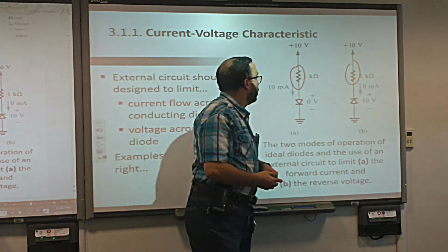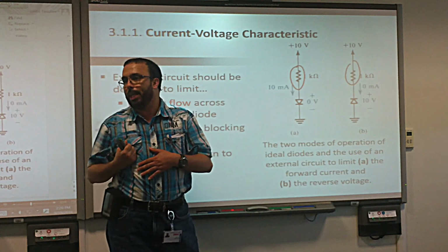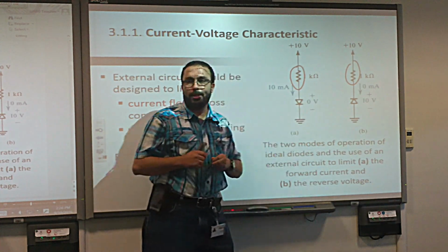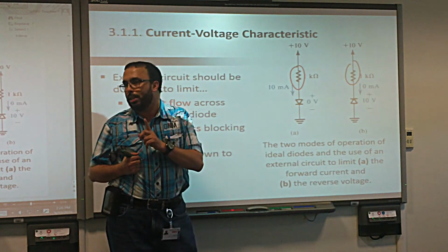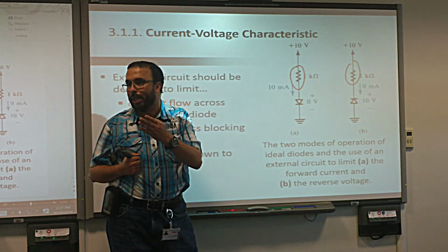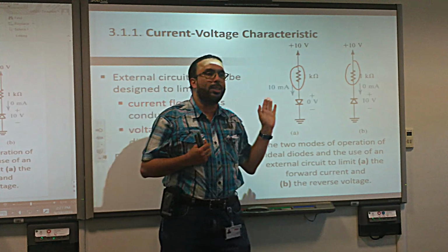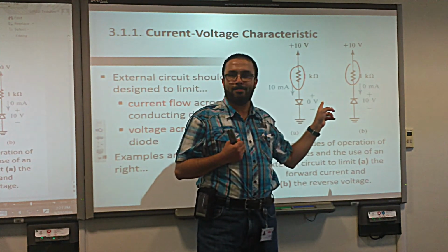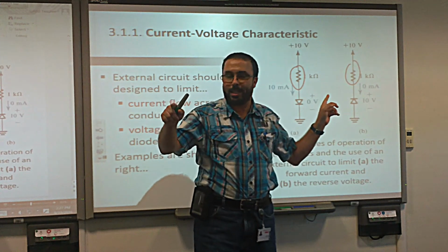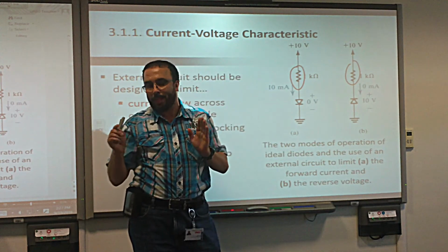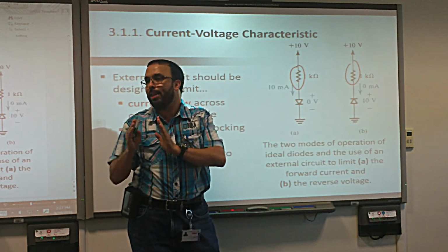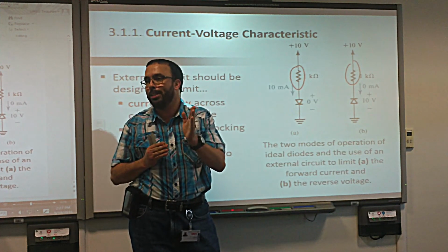Did we understand? So to study the diode behavior, we have to put what? A resistor in series with the diode. That means if the diode is in the short circuit form, or in forward bias, what's the role of the resistor in this case? Reduce the current. Exactly, limit. Reduce is right, but the right word is to limit, to make the current limited.